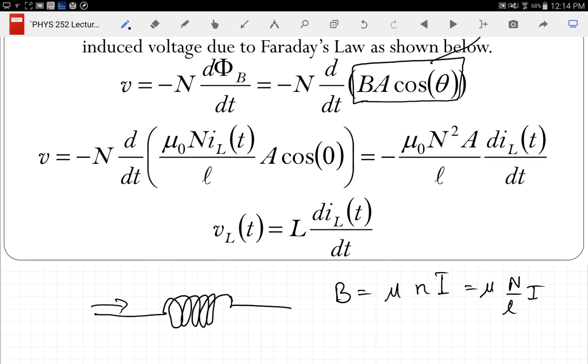I'm confused. So any given inductor is always going to have something introduced in? Okay, if you just take an inductor and you measure the resistance across it, you'll get close to zero, because it's just wire wrapped in a loop, and the resistance of the wire is very low. But when you put that in an AC circuit, and you're constantly changing the magnetic domains, you're constantly doing work to change those domains, and so you have energy loss that looks like a resistive loss. Because of the change in direction of the current. And it's occurring because of the changing direction of the current, yes.